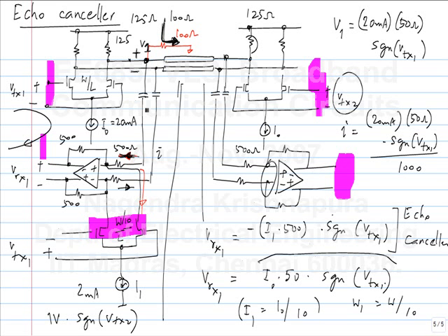But the more severe practical thing is the impedance is not real, so you will get a filtering action in the echo. So you can use this for first order cancellation, so that what you receive on this side is predominantly from this transmitter. And after that you can use an adaptive equalizer to do anything.